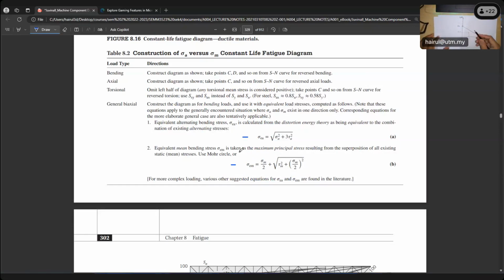So it is below, because this is the border, right? This is how you can find the safety factor by using the graph. This is your loading point. This is the 0, 0 point. Start from 0 like this to your point. So the safety factor is like this. You can use the graph also, because this is the border of your failure.